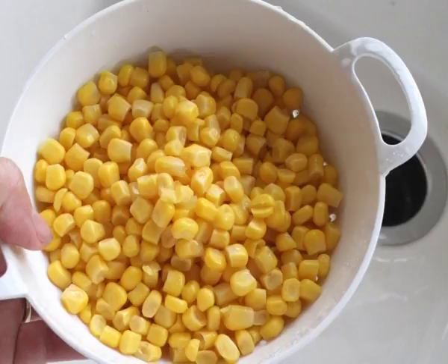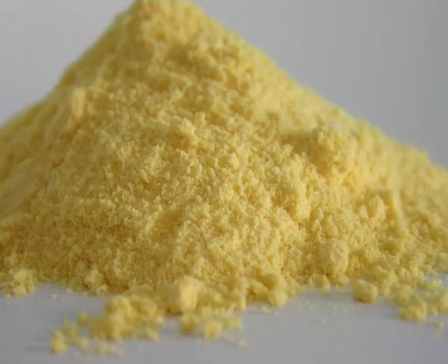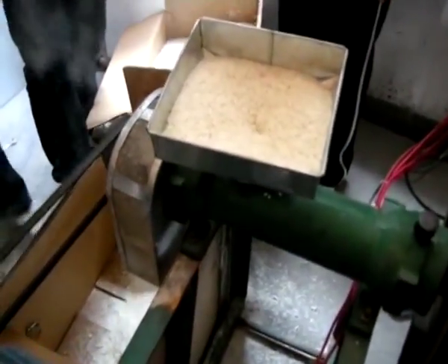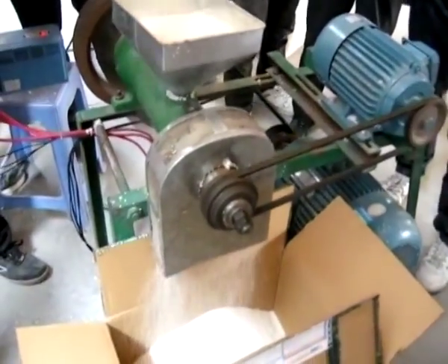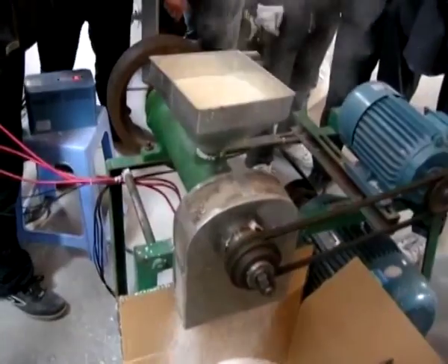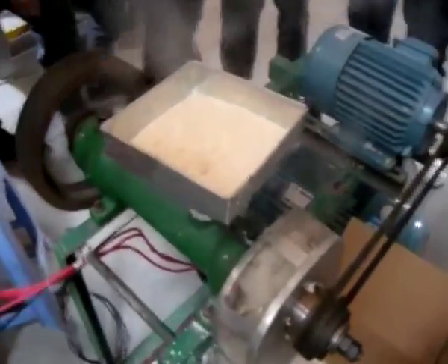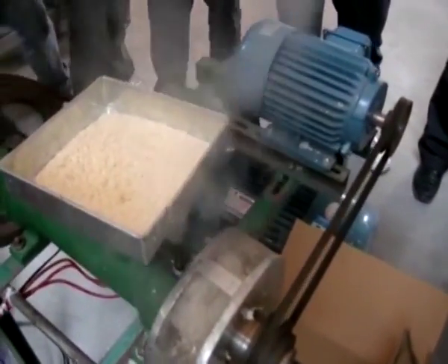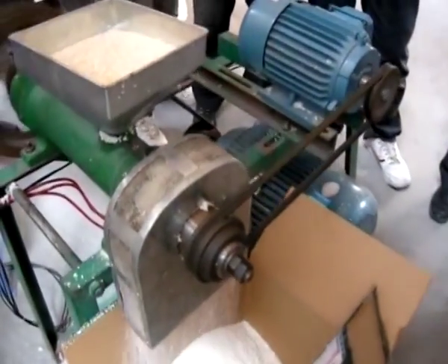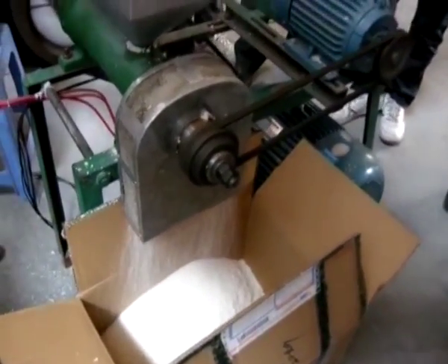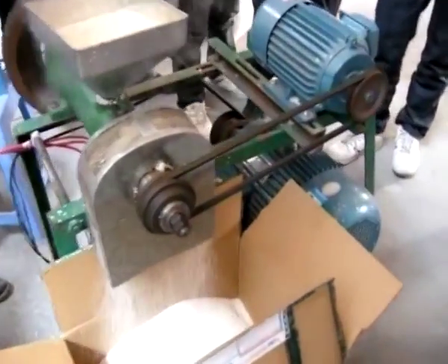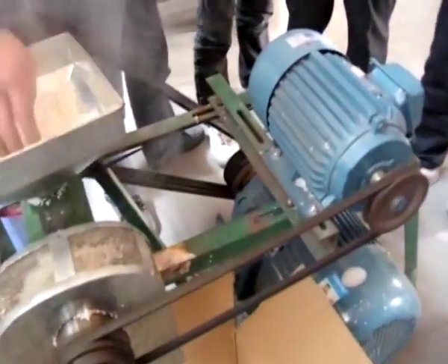After steeping, the steep water is drained off and the maize is coarsely ground in degerminating mills to free the germ from the grain. Then, the ground material flows down separating troughs in which hulls and grits settle while the germ overflows. The germ is then separated, dried and oil extracted by hydraulic pressing or by using a solvent. The degerminated material in the separating troughs is then finely ground in a buhr or attrition mill.